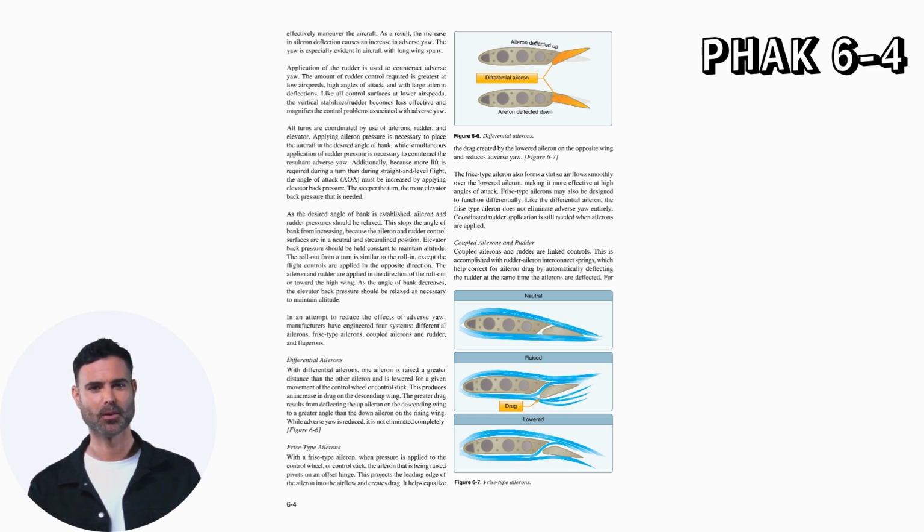As the desired angle of bank is established, aileron and rudder pressures should be relaxed. This stops the angle of bank from increasing, because the aileron and rudder control surfaces are in a neutral and streamlined position. Elevator back pressure should be held constant to maintain altitude.